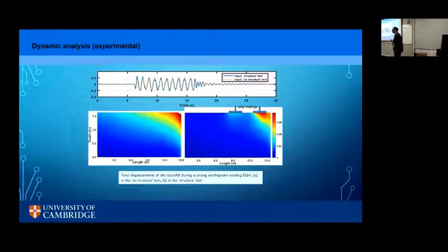This is the most interesting thing in this problem: what's happening to the displacements behind the wall. You would expect that the structure would make things a lot worse, and it does in terms of the bending moments. But if you look at just the wall itself, as before, we get big displacements behind the wall. Red is obviously large.